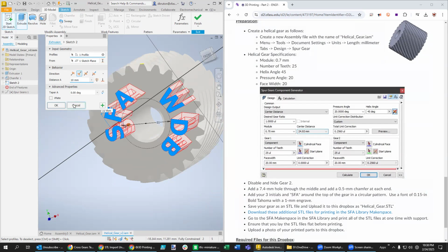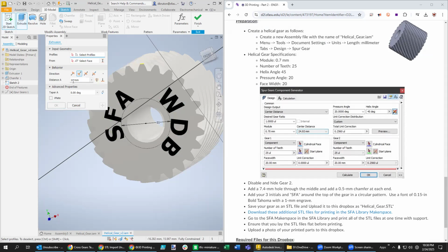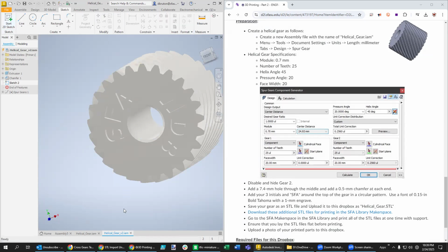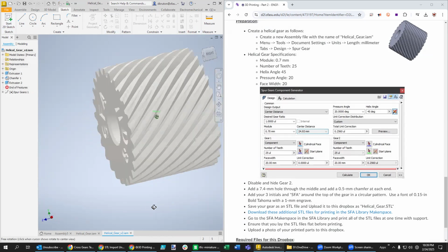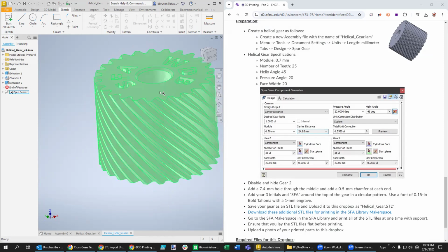But what we're going to do instead is go over here to engrave, if we can find it right here. Usually it's up here. I guess we'll just have to do a cut. And we're going to make it just 1 millimeter, in that direction. So it's still going to be visible after we print this, but it will not be outstanding. It won't be standing up or offset from the surface other than a cut.